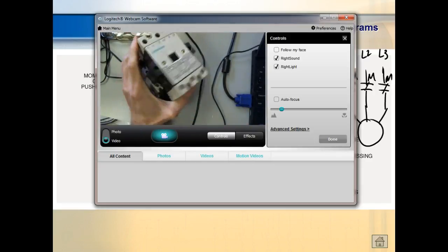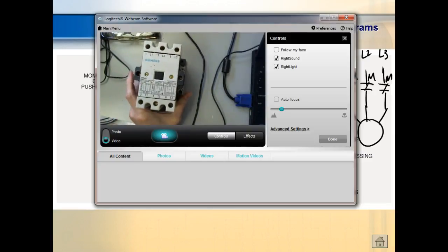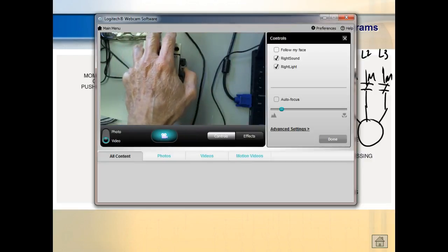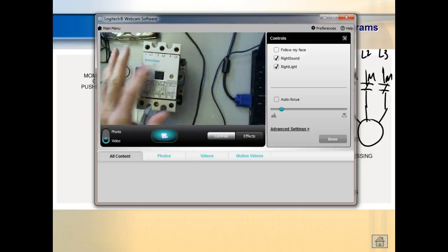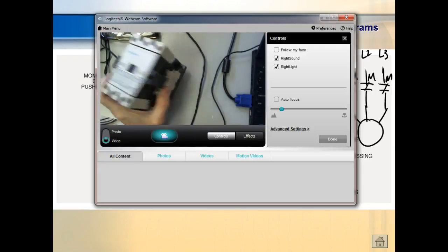Your new relays, by the way, you're not going to see the contacts. The contacts, and we'll talk about this later, are going to be inside of chutes. They're going to be sealed up. You can still maintain them, but we'd have to remove this cover to see the contacts, because we don't want to expose to the air something that's going to be arcing and sparking when it makes and breaks, right? And then we isolate the power contacts from each other, and we'll talk about that later.